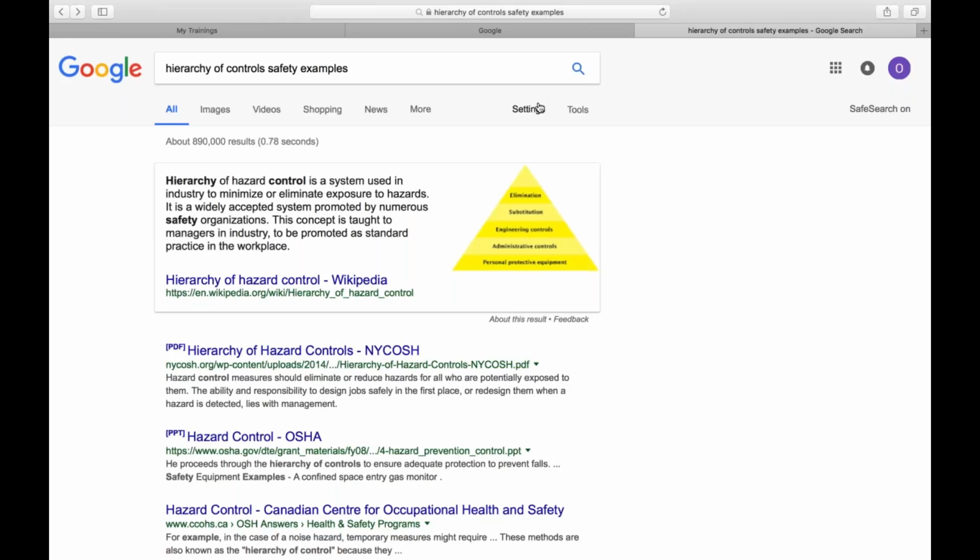So then, of course, PPE, right, folks? We also know that we have to have adequate PPE on site for our regular jobs, but also in order to respond or to evacuate during emergencies. It could be anything from any hazards like chemical splashes, right, or contact with toxic chemicals. It could be from falling objects or fine particulates or particles. It could be falls from elevations, unknown atmospheres that can contain toxic gases, vapors, mist, inadequate oxygen. So it could be inadequate oxygen or enriched oxygen, right? It could be explosive levels or flammable levels, and then it could be toxic chemicals as well, right?